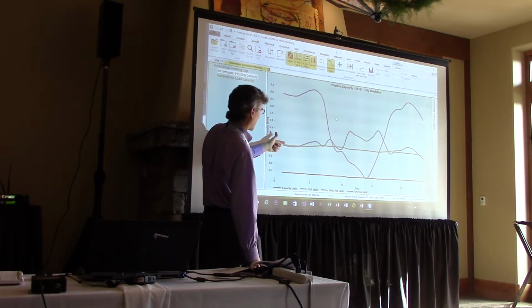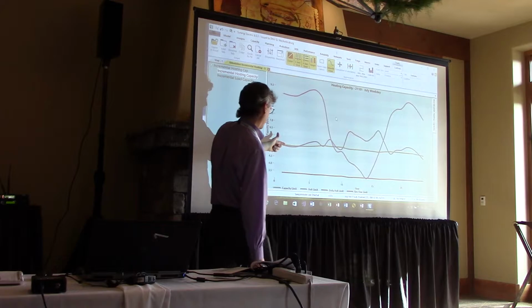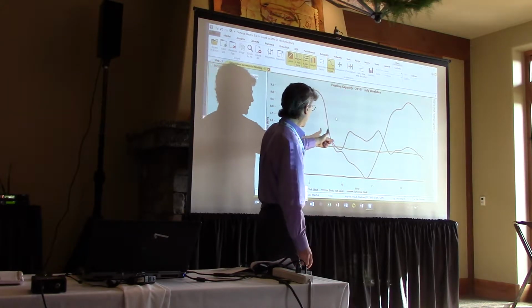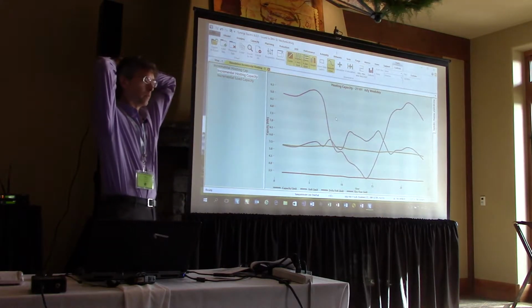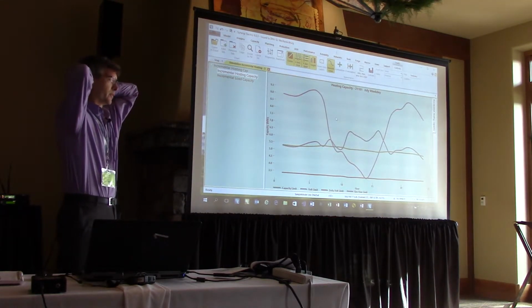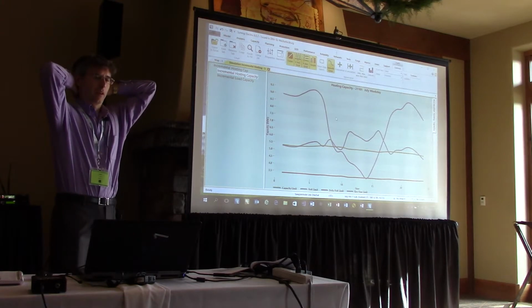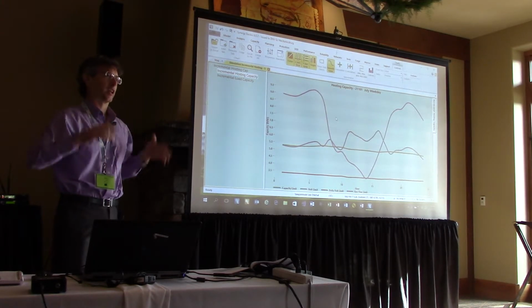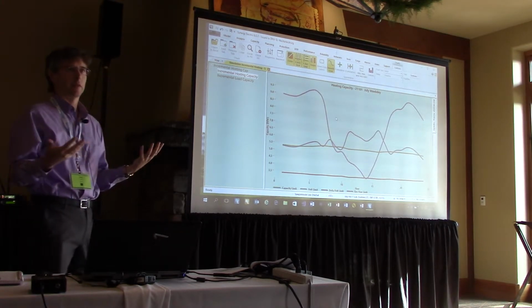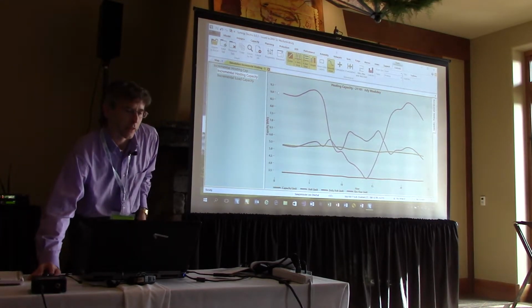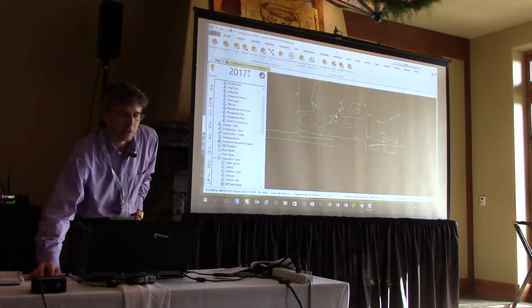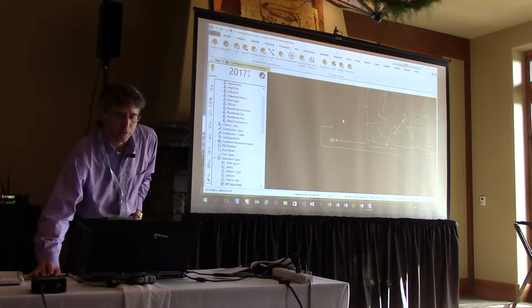And my thermal capacity is here. This is my low voltage limit here. Sorry, high voltage limit. We're going to put in low voltage on this thing too. And that seems like a weird thing to do if we're talking about PV. You know, it's a high voltage problem. Why are we worried about low voltage? And that's why I stress the fact that we are dealing with the substation, and it's important to model the substation in there.